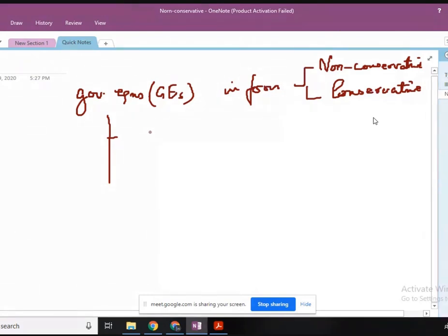So we discussed the flux being a part, the divergence theorem coming into the derivation, or the control volume approach coming into the derivation of the governing equations, which inherently makes it conservative because you are talking about what happened with a physical quantity. For example, what happened with mass flux, what happened with momentum flux, what happened with energy. So there was a collective combination of terms which is going to be tracked, or conserved. This is why such equations are known as conservative equations.